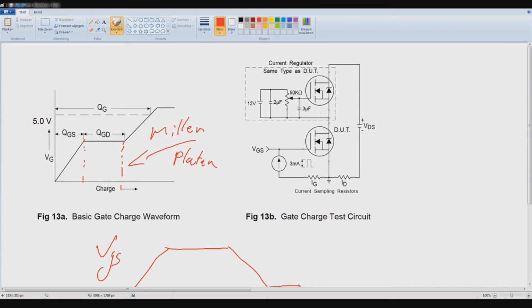where it's very visible and it can cause non-ZVS behavior. Therefore you have more efficiency losses because of this little dead time where it doesn't rise. Because if this was linear, you would just increase it like this, and then this is your maximum time, which is not the case.